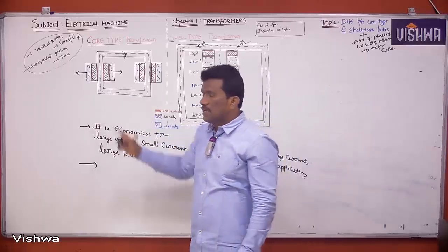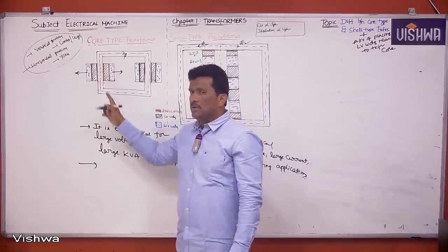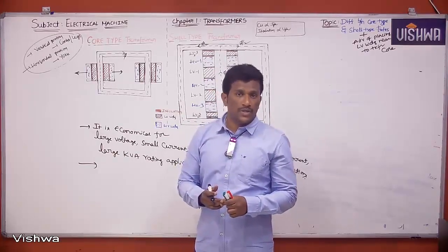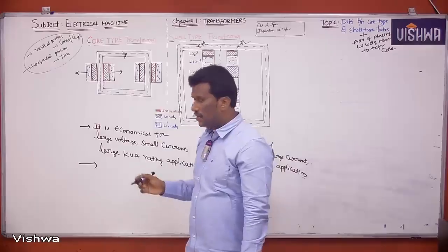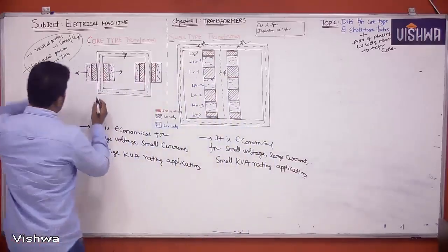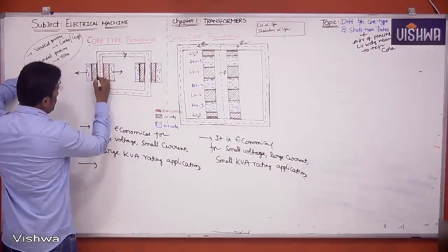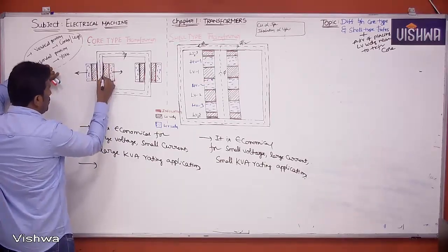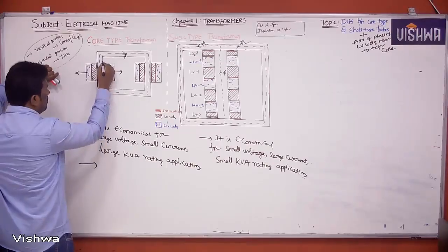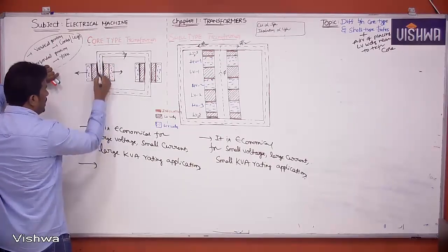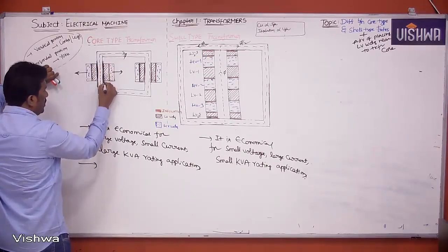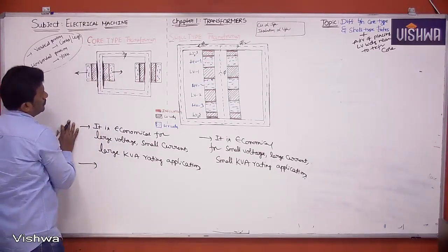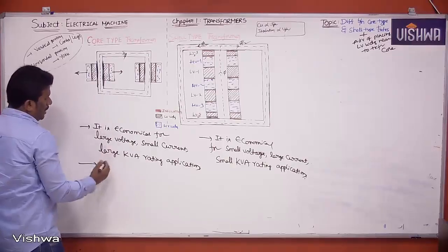Now here, the conclusion I can say is that since windings are placed on one limb, the direction of current will be opposite and a repulsive force will be there. Yes, repulsive like this. See, repulsive is just like this. You observe clearly, these repulsive forces are perpendicular to this limb. Is it correct or not? This is your limb on which you place your windings. This is perpendicular to your limb.